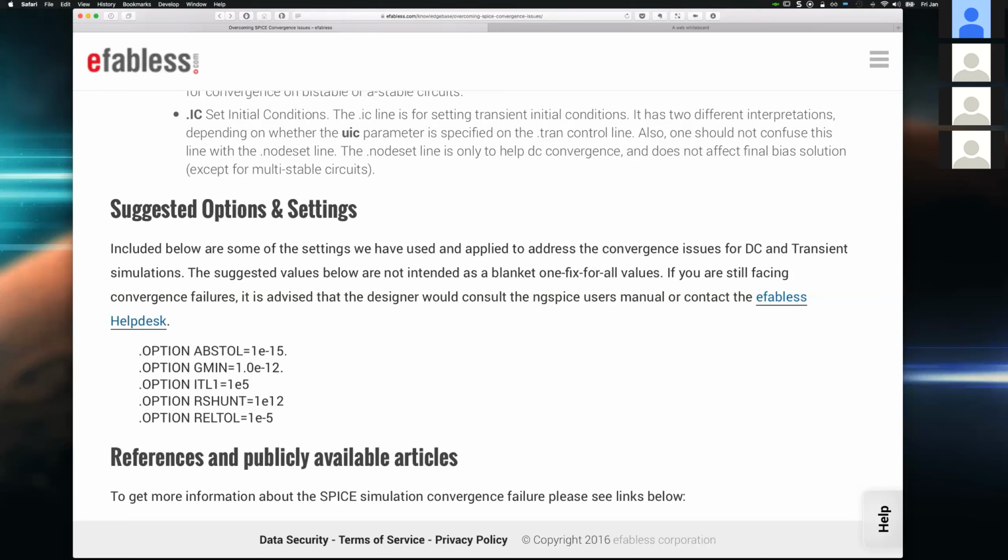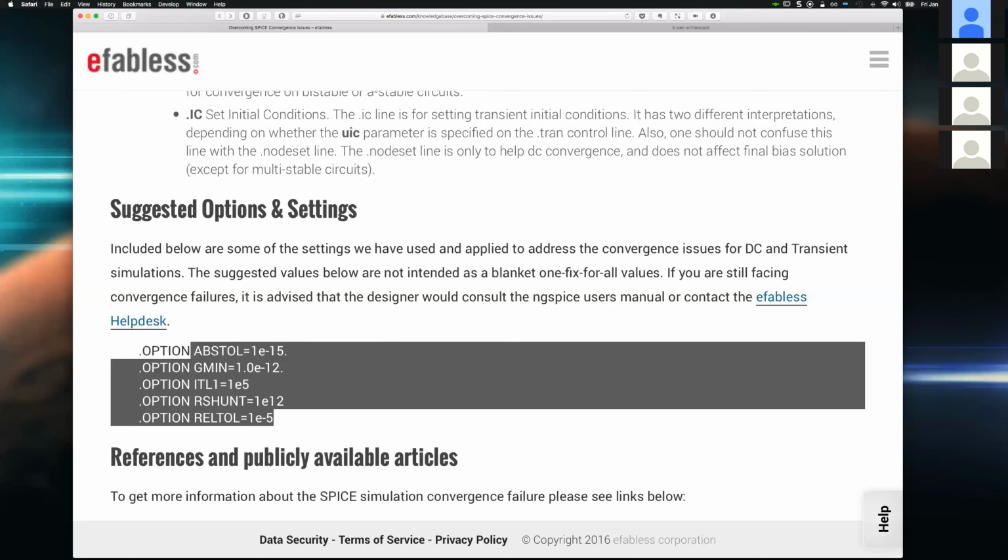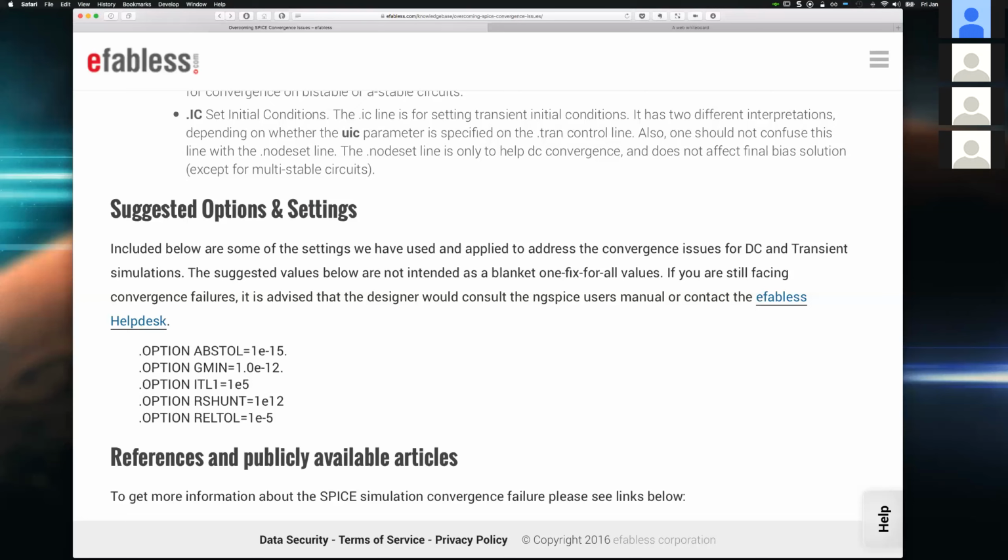Obviously everything is sensitive, but the sensitivity of the performance I'm measuring, whether it could be noise or transient response or whatever, should be low to these parameters, or lower than what I'm looking for in the system spec. If the system spec is within a certain range, sometimes very tight, then you can't have a high error tolerance. And obviously, if you get to that, it means the circuit is very sensitive, or the architecture being used is very sensitive anyway.